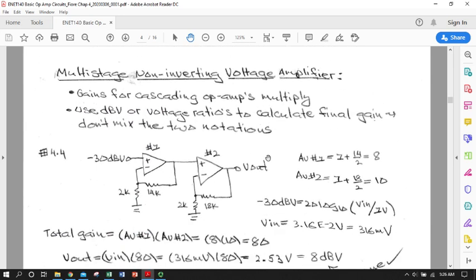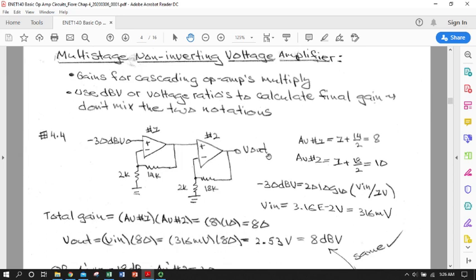Okay, so speaking of different amounts of gain, what if we need to get more gain than is available from a single op amp, and how would we know that we're at that limit? The best way, and we may or may not have touched on this already in chapter 3, is that if your calculated output voltage dropped over your load to ground exceeds your supply voltage, you will get the supply voltage. You'll be back to being just a comparator.